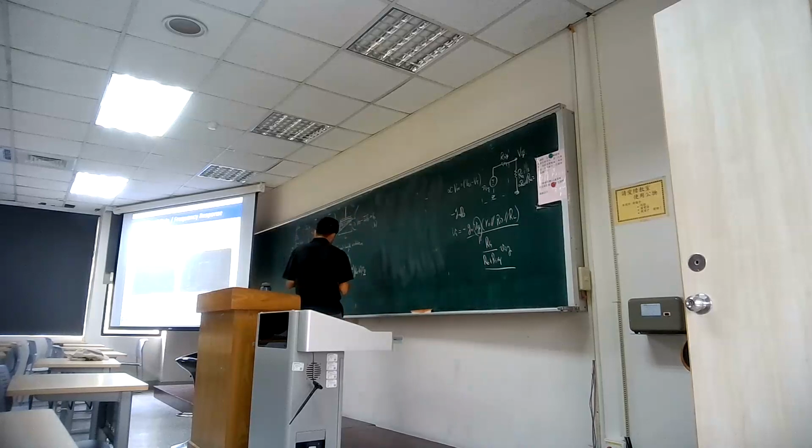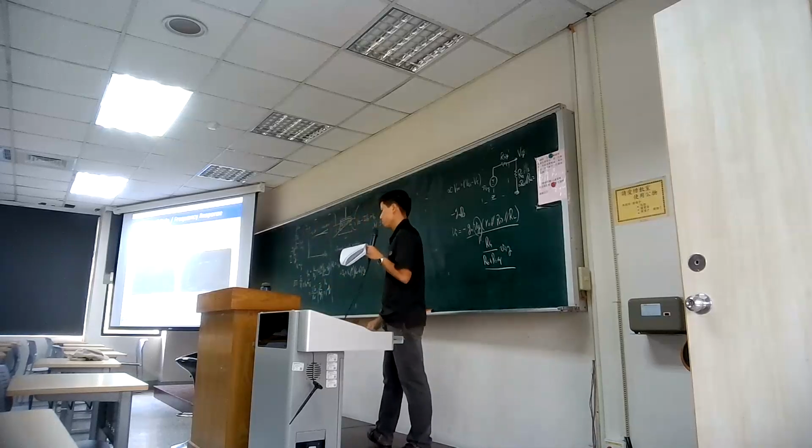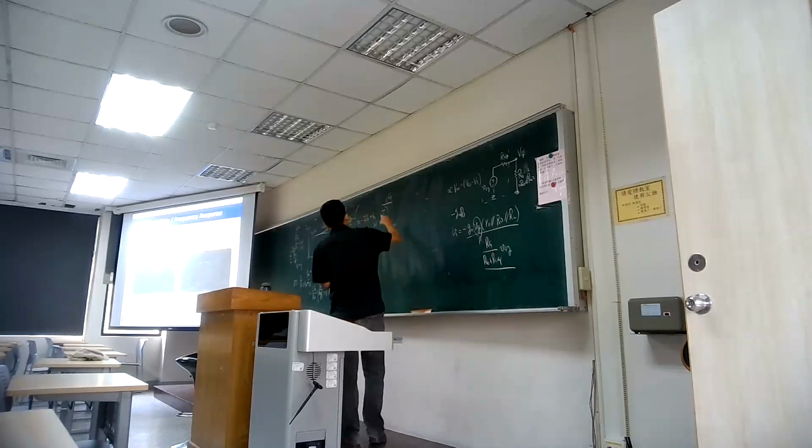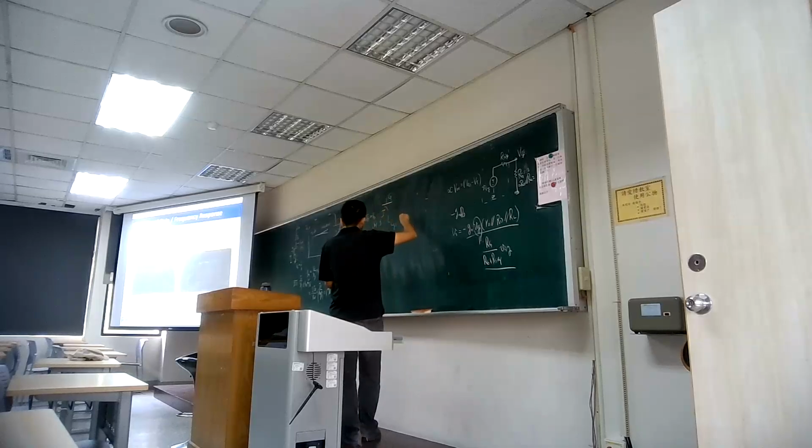And what is the capacitance here? So you can say the CGS, we can denote it by A, and then here is the source side. So there will be a capacitance from the CGS. Okay. And then how much is this CGS? It is a dielectric which is separated by oxide. So for this oxide capacitance, typically you know the area divided by the separation distance.